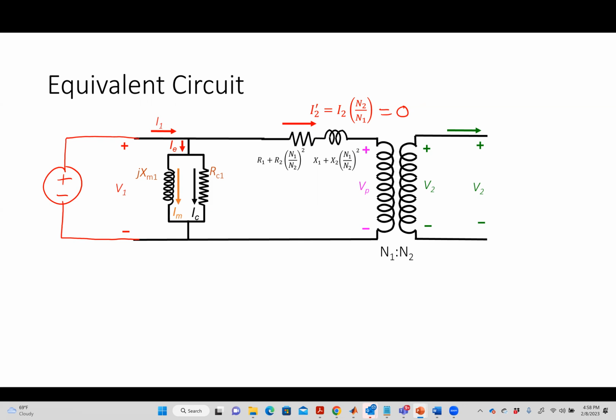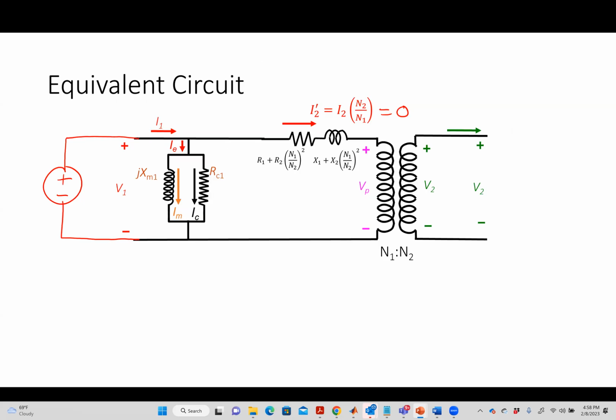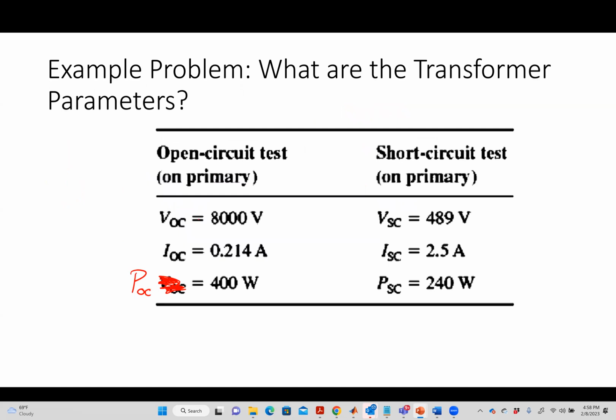When people figure out the parameters, and this is what you do from an engineering perspective, nobody knows the reluctances of the different paths or whatever. From an engineering perspective, what I typically just know is things like this. I do a test where I hook up a voltage source, VOC, I call it VOC, and I hook it up to the transformer.